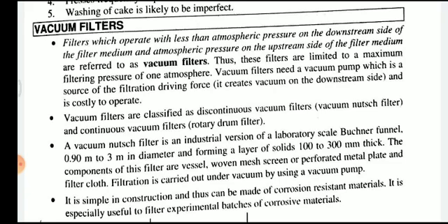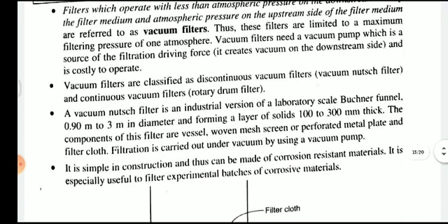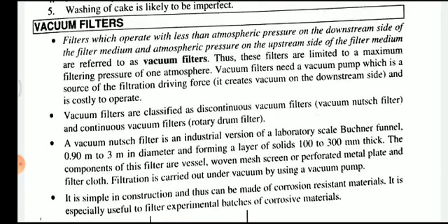That means on the upward side of the filter medium the pressure is only atmospheric pressure, with no other pressure acting on it, and below the filter medium, the downstream side, the pressure is less than atmospheric pressure. So it is called a vacuum filter.